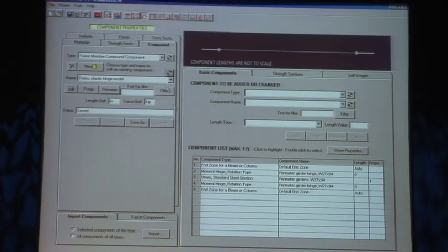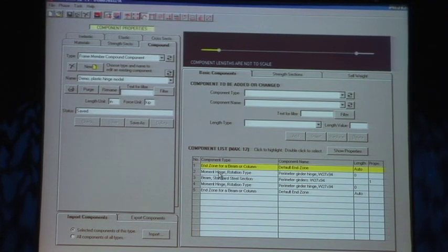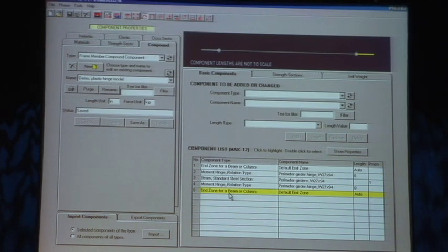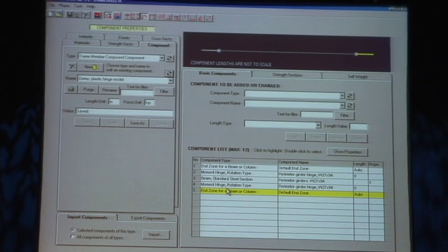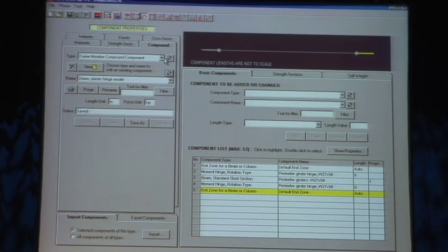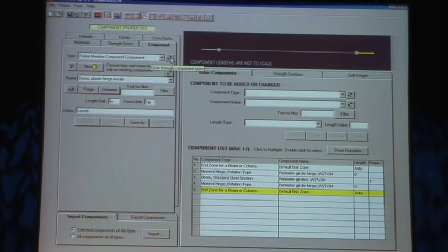That's the simplest model. You might also have a plastic hinge model, an end zone, which lights up yellow. I hope you can see that. And then a plastic hinge, then an elastic beam, and another plastic hinge, and an end zone. But you now have to come up with a plastic hinge rotation and capacities yourself because ASCE 41 doesn't give it to you. It's actually quite easy to get it for a concrete beam, a little more difficult for a steel beam.